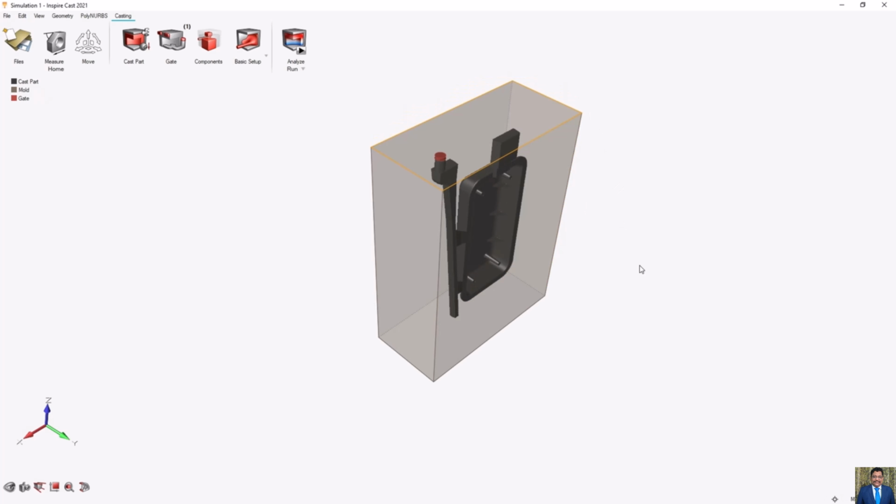Now I want to choose a speed for filling with the metal. If I go in basic here, I have the speed here, but we go 0.5 in speed. But be careful, sometimes you have it in millimeter, and if you have it in millimeter, when you go here, yeah, you can see, but you can change. We go in meter, and here is the filling time.